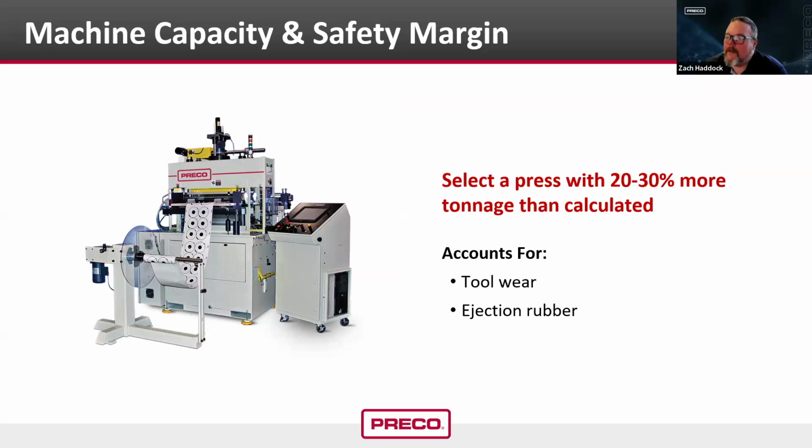Let's talk about machine capacity and that safety margin. That is my 80% rule. What I mean by the 80% rule is I don't like to soak up more than 80% of the available tonnage on my press. The reason for that is if I'm doing that shoot from the hip calculation, I'm usually not figuring in the ejection rubber.